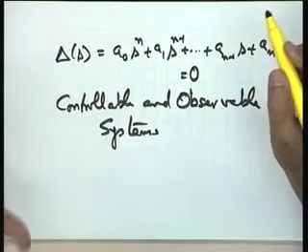And since he has raised a point, please note that it is only under this assumption that zeros do not cancel a pole that BIBO stability is same as asymptotic stability, otherwise the two concepts are different. Because if a 0 cancels a pole, BIBO stability will not show that, because the pole has been cancelled.